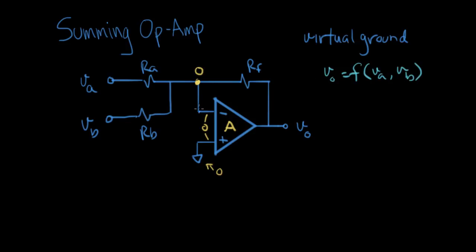Looking at my circuit, the other thing I know about op-amps that's really important always is that the current going into an op-amp input is 0 or practically 0. And for the purposes of what we're doing here, we can treat it as 0. So we have 0 volts on this node, and we have 0 current going this way. So let's go after this current right here.